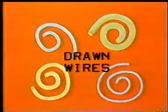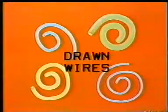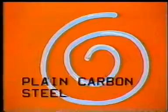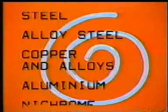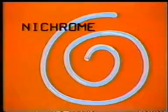The wires obtained by this process have much higher tolerances and better surface finish. The process is especially useful for producing electrical wires of plain carbon steel, alloy steel, copper and alloys, aluminum, and nichrome. This completes the method of metal forming, its principle and processes.